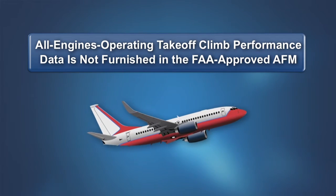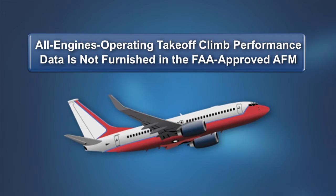This is not a subject addressed by the certification rules. Therefore, all engines operating takeoff climb performance data is not furnished in the FAA-approved airplane flight manual. As we have seen, there is a requirement to furnish one-engine-inoperative climb performance data in the AFM, but using this data to show compliance with a climb requirement published on the IFR departure procedure is not required by any operating regulation.